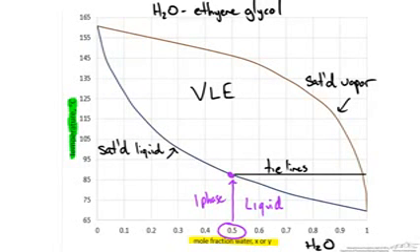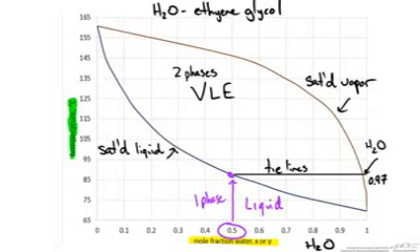In this case, when we go from one phase of liquid and we hit our saturated liquid line around 87 degrees, we could draw a horizontal line to our vapor line to determine the composition of that first droplet of vapor. In this case, enriched in water with a mole fraction of 0.97. So let's say we keep increasing the temperature for our mixture.